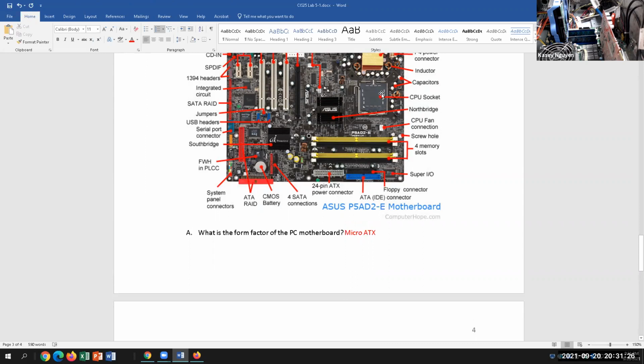That's the normal ATX. That should be on the bottom, because the cool air is going to pull in and hit the RAM. The RAM is always going to be parallel with your socket. So on the ATX, the way we design the motherboard now is RAM is parallel to the processor. Expansion buses are perpendicular to the processor for cooling reasons.